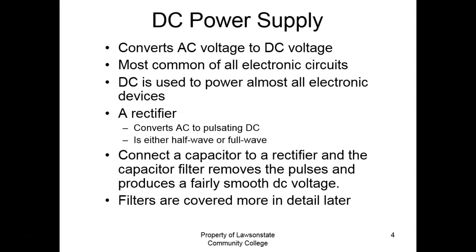In fact, if you look at it in that small print, it would say 120 to 250 volts AC in, and it would say so many volts DC, but 5 volts because they charge off USB. USB puts out 5 volts. It would say 5 volts, and then give you a current rating on it, if you look at it close enough. So that's a DC power supply. All those little cubes you charge up with, that's the AC to DC power supply. So right now, if I was to cut this cord and measure the two power leads on this thing, it would measure 5 volts.